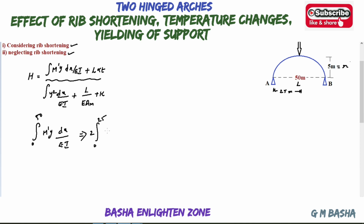See here, M dash y dx by EI. What is M dash here? M dash is the moment. For finding M dash, first consider a point P with coordinates x, y. Consider section XX at a distance of x from here, and this one is y, and this central rise is equal to 5 meters.